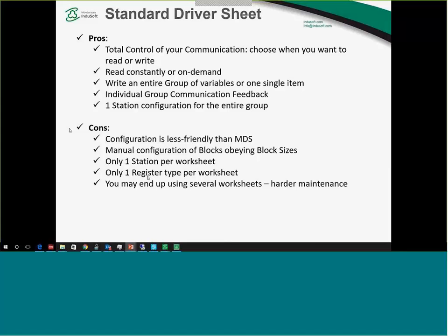And you configure only one station per worksheet and only one register type. That means if I want to talk to the 4X and to the 3X, I have to have two different worksheets. And because of the block size, if I want to talk to the 4X, or let's say 40,100 and 40,300, there's a gap of 200 words there. I may need to have two driver sheets. This may cause you to end up using several worksheets, which is harder to maintain.